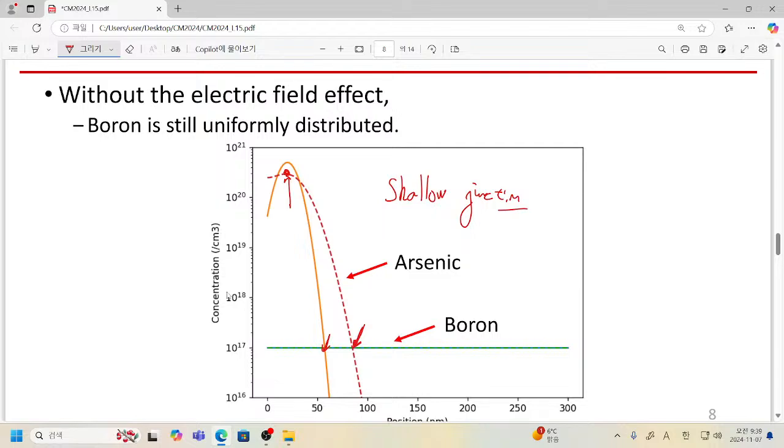So that's the reason why we introduce a low energy ion implantation to our dopants. So we wanted to make quite a shallow junction. However, in order to activate these dopants, we must apply certain heat, and it introduces a certain redistribution of our dopants inside the semiconductor substrate. So anyway, that is the situation we can expect from our diffusion simulation.